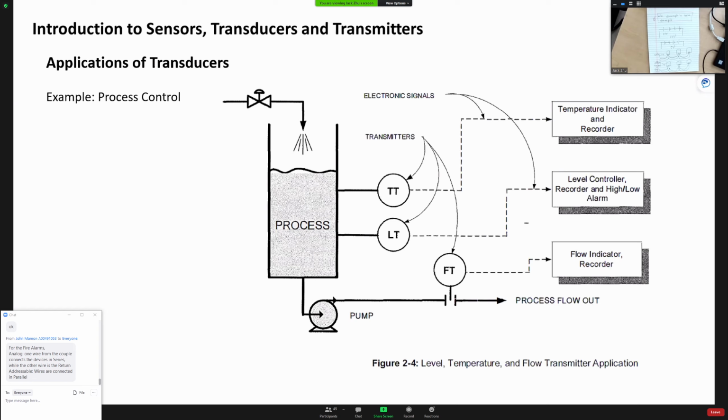But at the time when I did them, those annunciation devices like the bells, horns and strobes still used analog, so you need to use wire to connect them. Usually for the analog devices, you have to put the end of line resistor down there, so the system can check there's no open wiring or no short across the wire down there. You're probably going to learn more detail in the fire alarm course when Jeff teaches you those things.